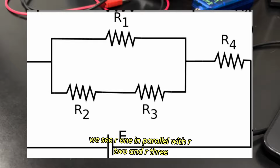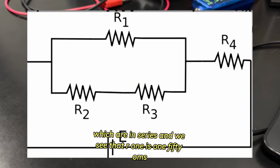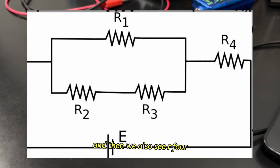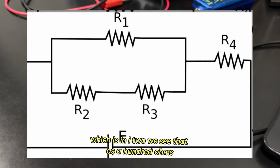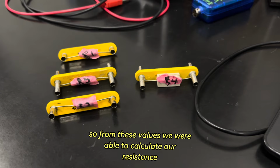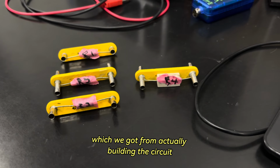In I1, we see R1 in parallel with R2 and R3, which are in series, and we see that R1 is 150 ohms, R2 is 680 ohms, and R3 is 560 ohms. And then we also see R4, which is in I2, and that is 100 ohms, and that one is connected to a power supply of 7 volts. So from these values, we were able to calculate our resistance, which we got from actually building the circuit.